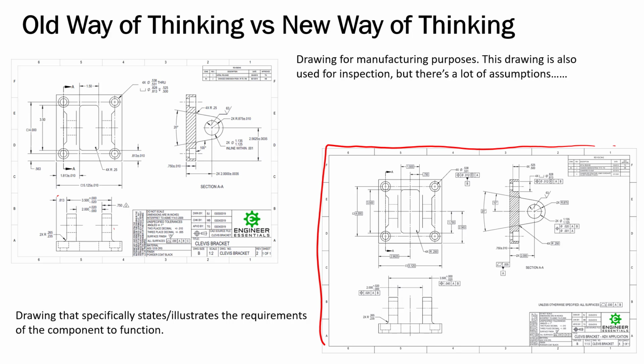If they don't understand the GD&T, it can cause prices to go up. I've dealt with this personally. So it can cause your prices to go up. I've also had vendors just give no quotes. They see the GD&T on there, they think that it's too complex, so they'll no quote it. And then I've also had vendors that don't know the GD&T on the print. They don't understand it. They don't want to take the time to ask about it.